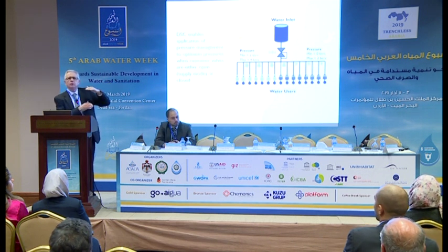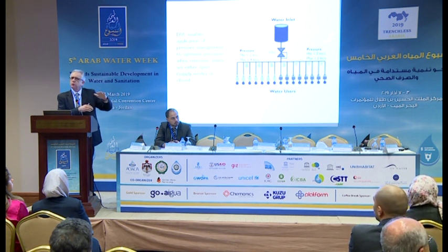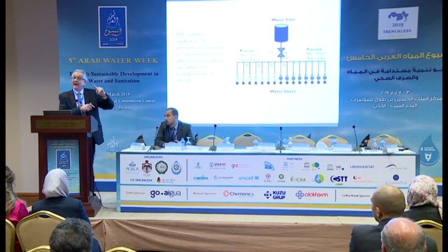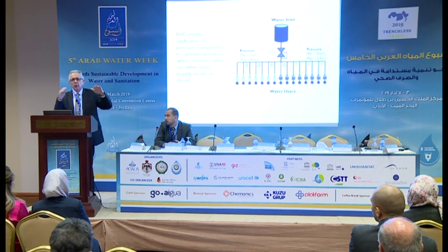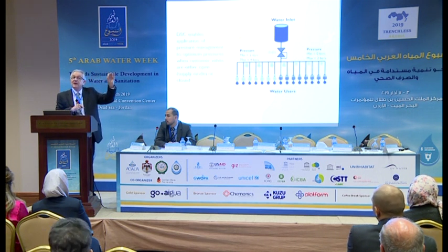So once we don't supply water to the customer, what can we do? We can reduce the pressure in the network. Not empty that part of the network, but reduce it. So the only pressure in the network is the static pressure given by the elevation in that particular area. But at the very high point, we just maintain 0.